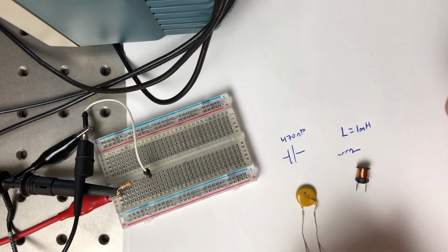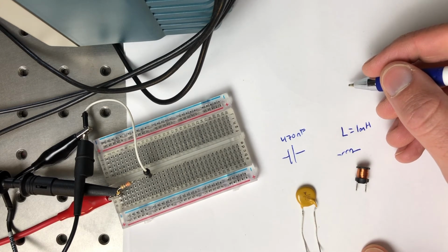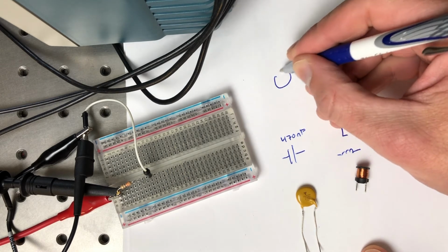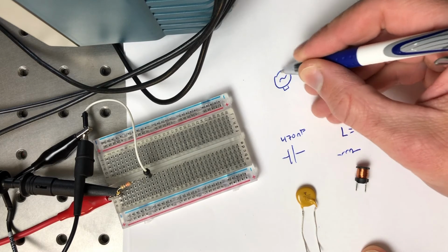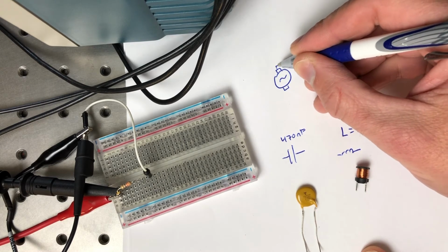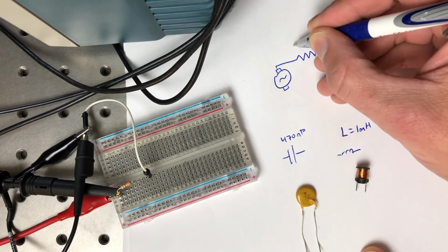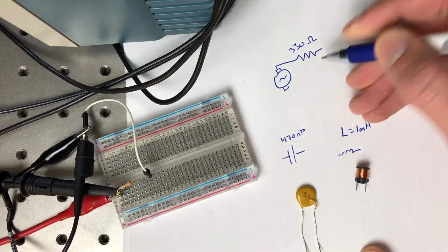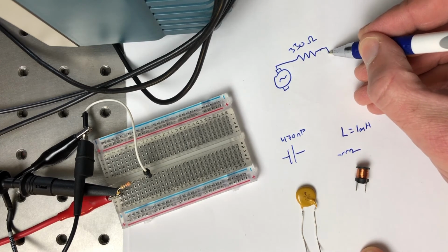So we'll start with an inductor here. Now the problem is, to measure the current, we need to use a trick. I have an oscilloscope, but it does not measure current. But what we're going to do is we'll have our circuit that's going to give me my AC voltage, my sine wave. And I'm going to put a resistor here, and that resistor's sole job is going to be to measure the voltage drop across it, and therefore the current through this series circuit.